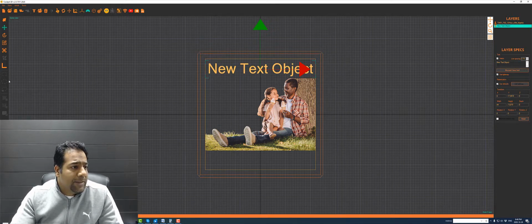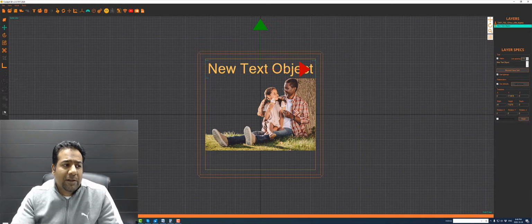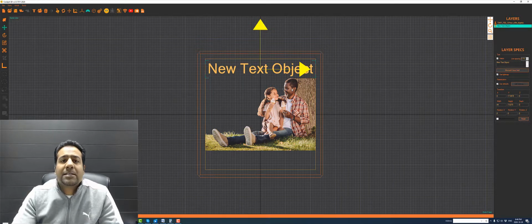All right, now these here will allow you to actually cut the model. So if you want to cut parts of the model out, you can do so with these icons here. You'll notice that currently they are not active because we're looking at the geometry file, right? The geometry file with all the polygons won't allow me to easily edit it. It needs to be a point cloud. If I convert this to a point cloud, I can then start trimming. So let me just click on Go.